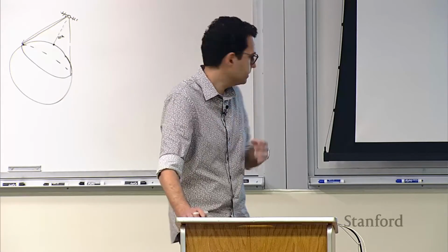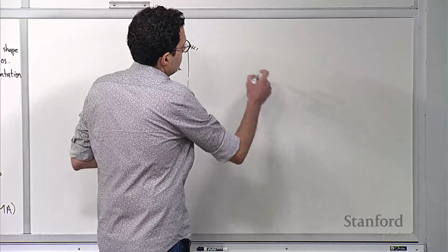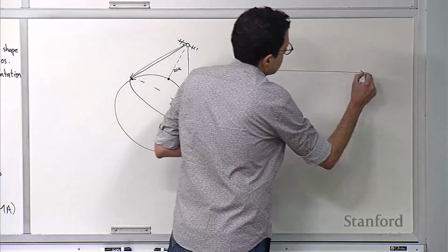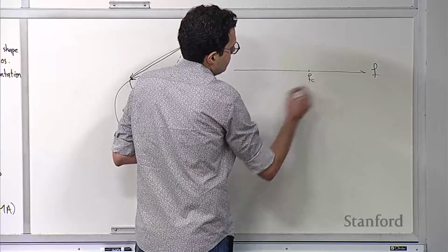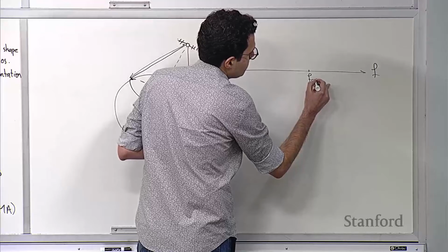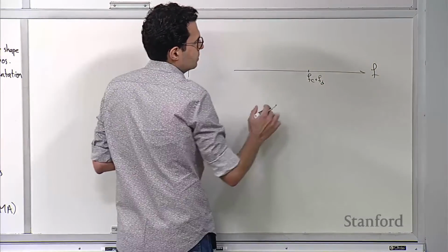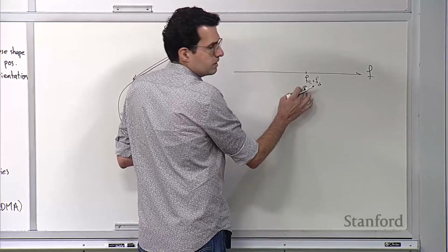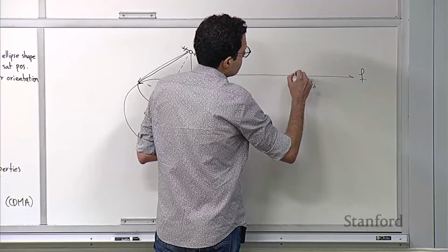So you first bring it, if I were to draw a picture of the spectrum, so if this is f, what you receive first is centered at fc, which is your carrier frequency. Well, technically fc plus the Doppler shift, but Doppler shift is small relative to your carrier frequency. This is kilohertz, carrier is gigahertz, right? But anyway, you have some signal around this.